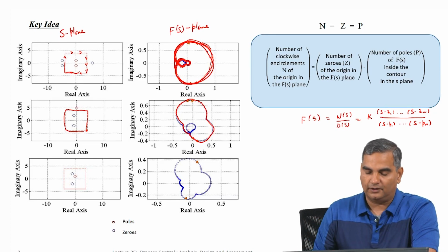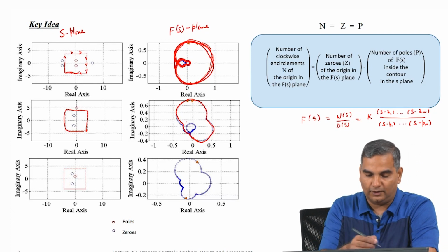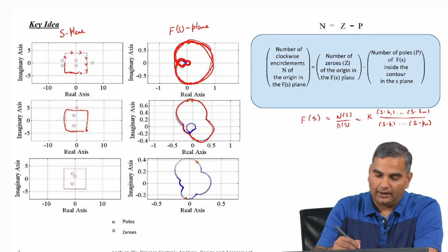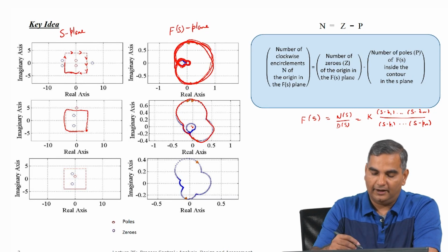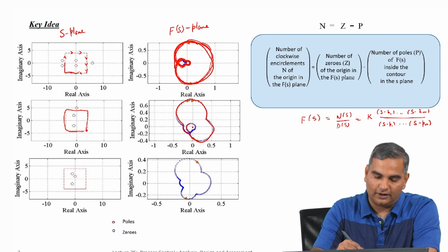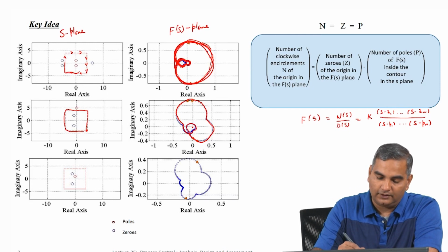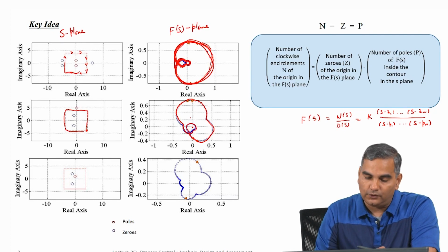Okay. So, this is the first contour, still this is not finished. As I move along, there is more to do here, that is what these plots show. Now, if you again look at just the outer part, you will see the origin is here, and I have encircled the origin once, but now in the clockwise direction, okay, and I am not done yet. I have to still continue around here and come back and stop here. This is when this whole thing has come back to its initial location. Now, if you notice, after making one encirclement, I come back again and make another encirclement of the origin, and that is also in the clockwise direction.